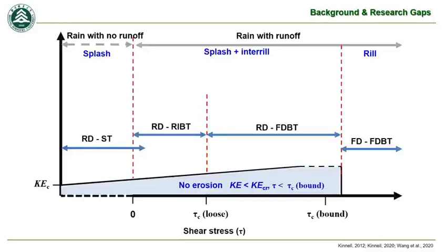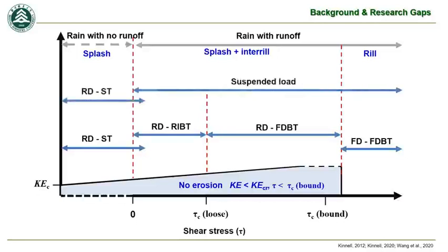In rain-impacted flow, coarse material, particularly sand and soil aggregates, can be moved by raindrop-induced sorting, raindrop-induced rolling, and flow-driven sorting and flow-driven rolling. Before meeting those critical conditions, coarse material can be moved by raindrop-driven sorting and rolling. Whenever detachment occurs, either by the expenditure of raindrop or flow energy, fine material is moved in complete suspension loads.